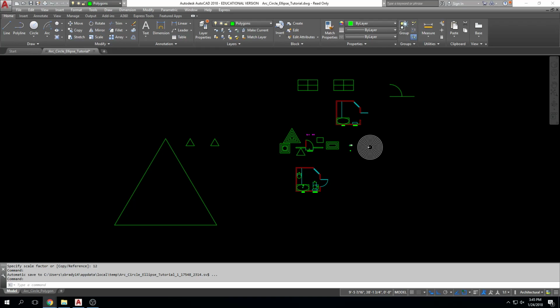Okay. And wide might be something, when drawings are printed, wide might look very wide like that. And heavy, instead of being 3 thicknesses, it might be 2 thicknesses. A medium might be 1 thickness, right? And thin might be the edge of my pen, which is like that. And then light is just the lightest little line, and fine is even finer. If I can get it with a marker, we'll just leave little dots in between.